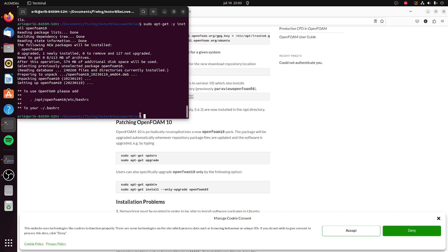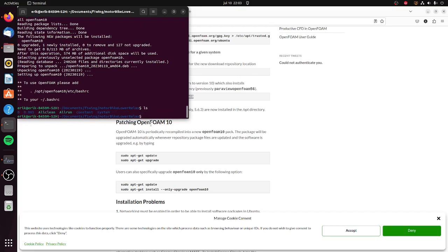So this is something that did puzzle me for a second. I didn't fully understand it. But basically, when I type run OpenFOAM into my command line, how does it know what I actually want it to do? The way to do that is that you need to go into your bashrc file or text document and tell it that's what you want it to do. But where is it? Great question. It wants us to add this, so let's just copy this for now. Again, you have to do Control Shift C to grab it.